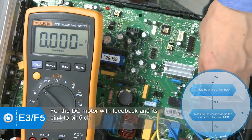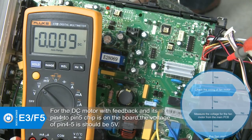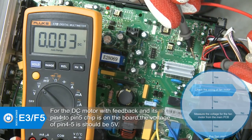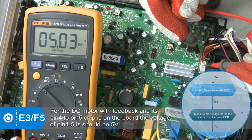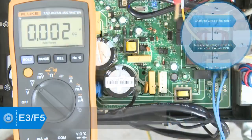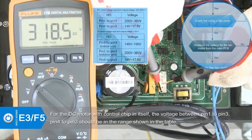Examination for main PCB board. DC motor with feedback and its control chip is on the board. Turn the power on. When the unit is in standby mode, measure the voltage of pin 4 to 5 in the feedback signal connector.